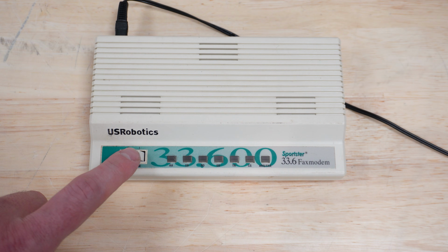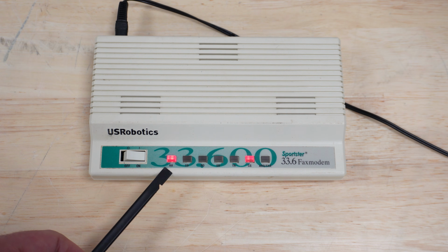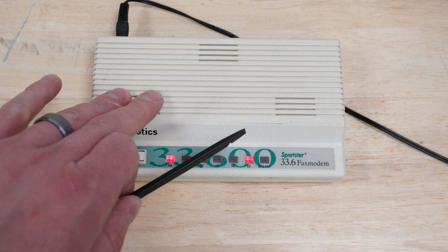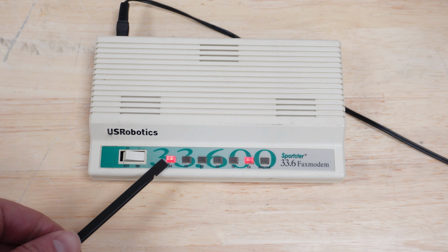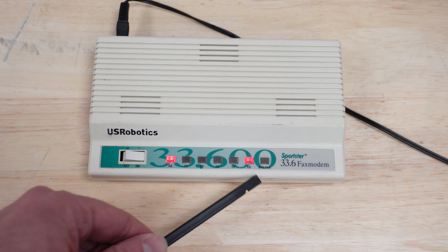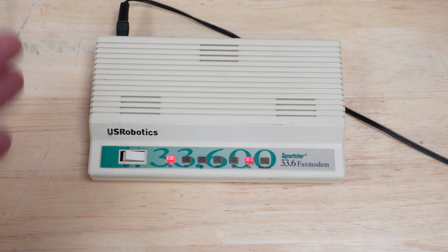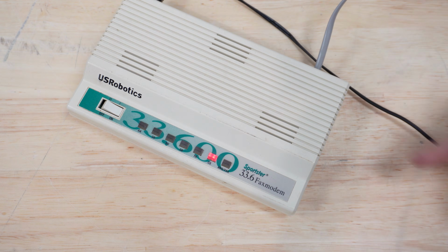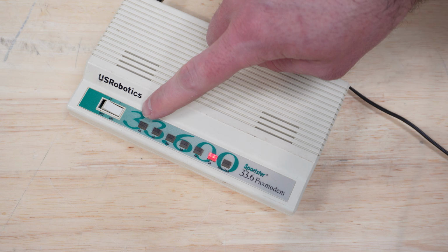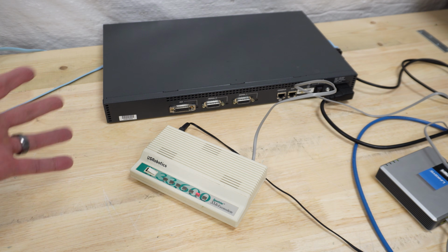Here's the older one that was working. It behaves a lot better. It's got this AA lit up, which is correct. That stands for auto answer, meaning if someone dials to this modem over the phone line, it's going to pick up the call right away. It's been configured for that with its jumpers, so that makes sense. I think CS stands for clear to send. I think that just means that the thing is ready. So it seems okay. Let's get a phone line plugged in. For some reason, AA turns off. Maybe that's normal.